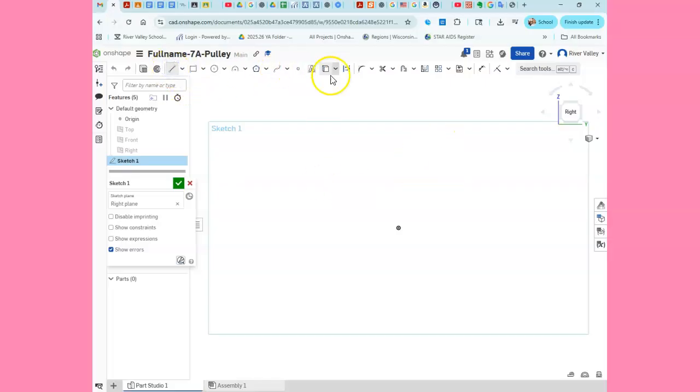And we're going to click on Line Tool and go ahead and click on the construction. We're just going to pull a line off to the right here. Hit Escape. We can go ahead and create another line going vertical. Hit Escape there. We're going to put a line, our bottom line, and establish our hole diameter. So we'll go ahead and create a line here.